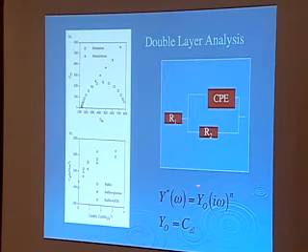And what we're interested in is this Y naught value right there, which would be equal to the double layer capacitance plus any other capacitances that were in parallel with that double layer capacitance. And so if that's not changing, the double layer capacitance can't be changing. So we fit it to this simple circuit since that's all we're after. And we have a good fitting program to do this. It's a nonlinear least squares. So that's the semicircle that you get out of that fit, by the way.